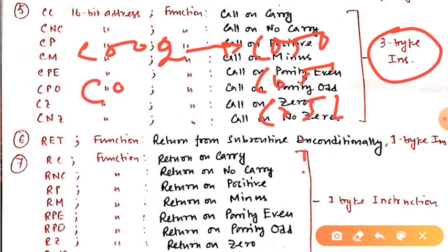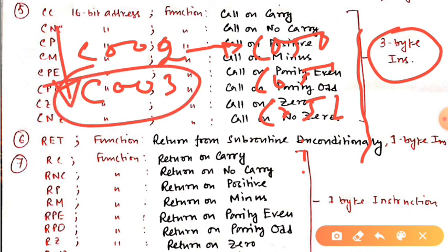So we hope that after finishing all the instructions written in this particular subroutine, we will come back to our original stream of program execution, that is to the memory address C003. That is why we have used the call instruction, because the call instruction saves this particular address. Otherwise we could have used the jump instruction, if we did not expect to come back again. But we are expecting to come back again and execute all the instructions written in this main stream of the program.